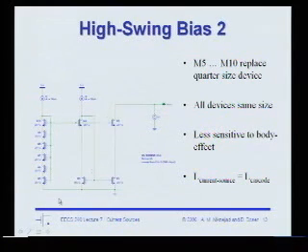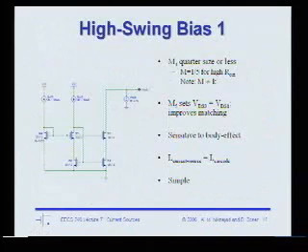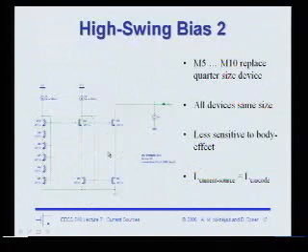And an implementation that we looked at last lecture, which is less sensitive to body effects, is essentially the same as this circuit, where we generate the right bias voltage by using a quarter-sized device, but then the observation is that these two devices basically don't match. Their threshold voltages don't match because this source voltage is pulled up. Also, to get the maximum matching between the mirror, we insert this transistor, which lowers the drain voltage to 1 overdrive, the same as this device. And then this is a variation on that principle.